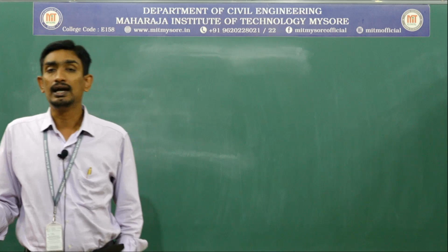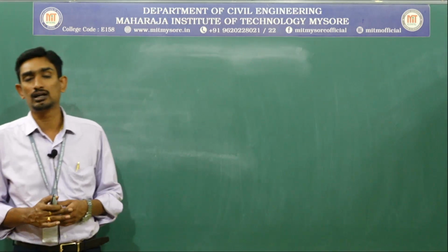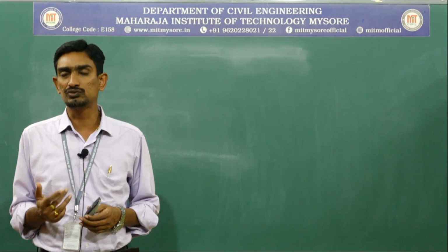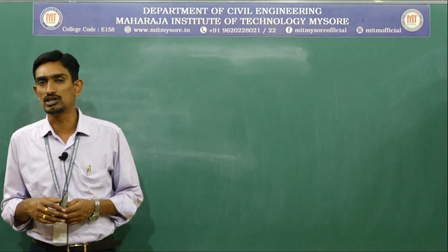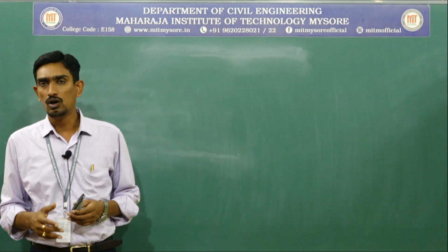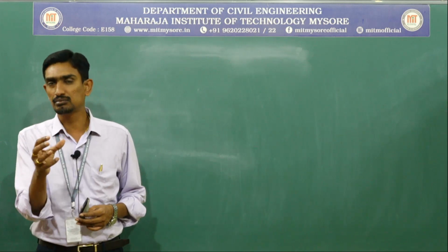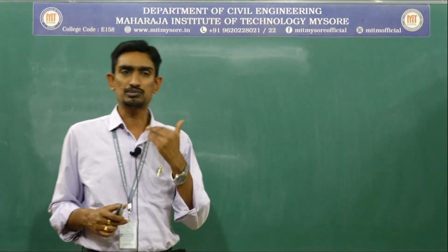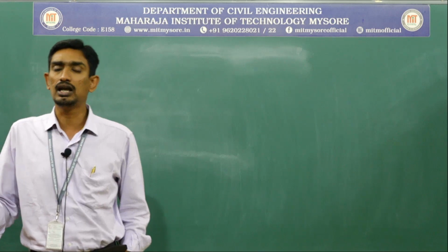This powdered burnt clay is a waste product when the brick is overburned, which is not useful in the production of bricks or wall construction material. Those bricks are powdered to form powdered burnt clay, which can be used as a pozzolanic material, and this was predominantly used in olden days.